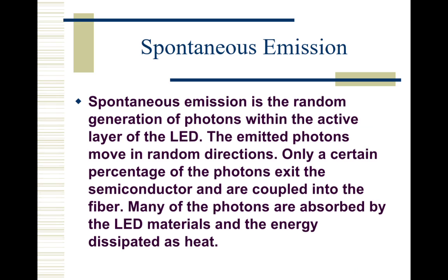The emitted photons move in random directions. Only a certain percentage of the photons exit the semiconductor and are coupled into the fiber. Many of the photons are absorbed by the LED's material and the energy is dissipated as heat. So that is called spontaneous emission. Spontaneous emission means light will be generated anywhere and it will be converted into photon energy. We will study how to convert that light into photon energy.